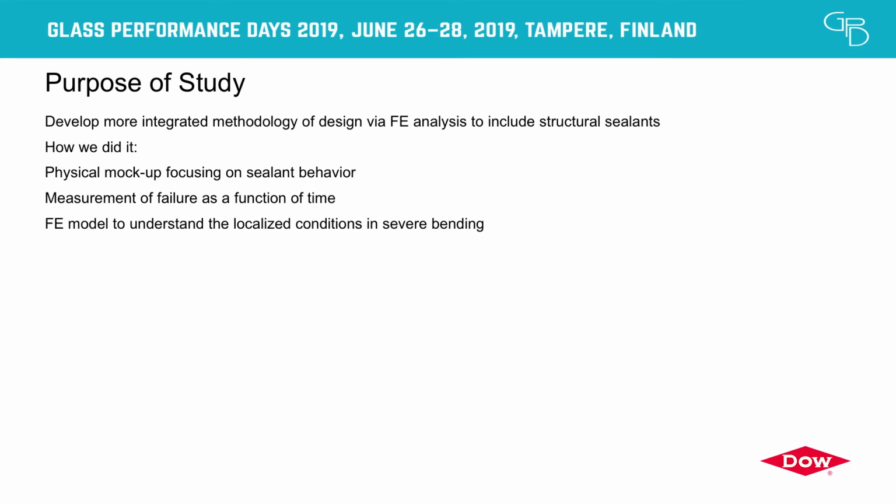We did that by building physical mock-ups, focusing on the sealant behavior. We measured the deformation over time. We also measured some of the crack propagation, so after it failed, we looked at how quickly it fails. And then we also did FE models to validate our physical mock-ups and make sure that there was alignment here.